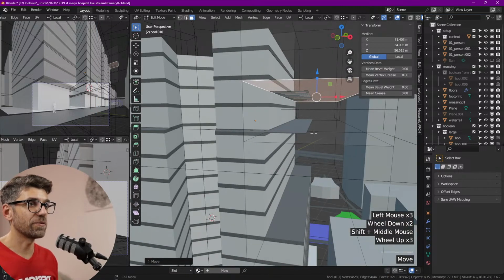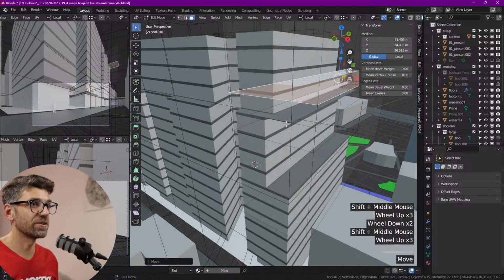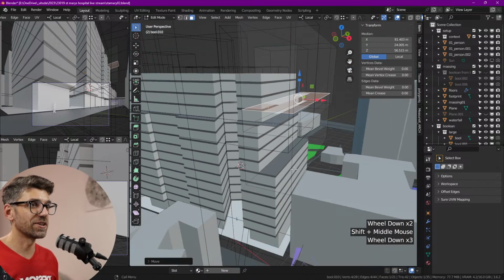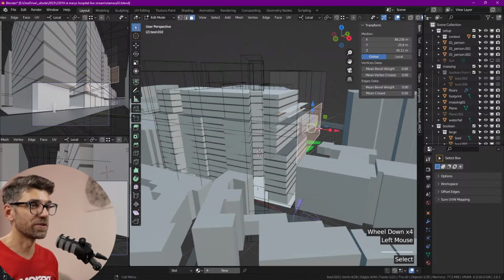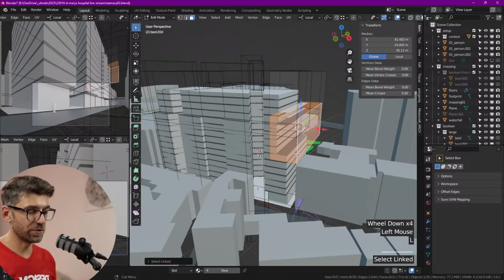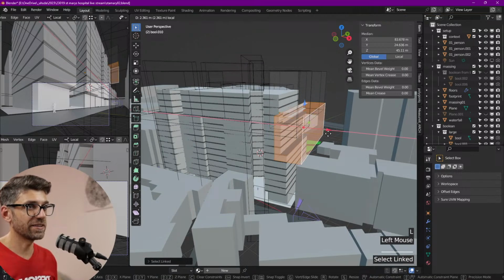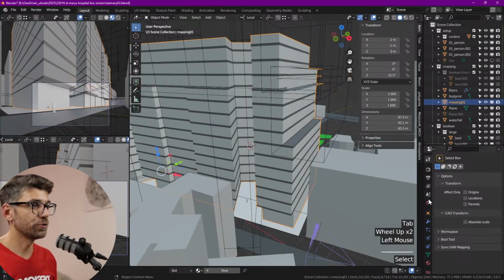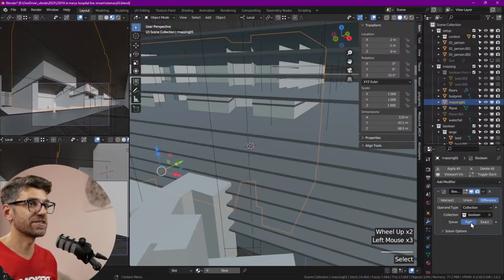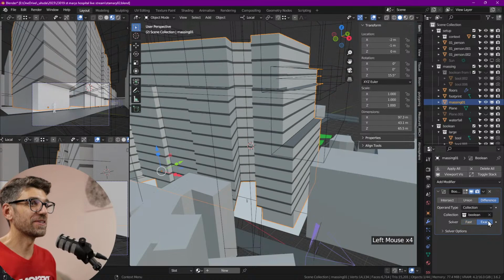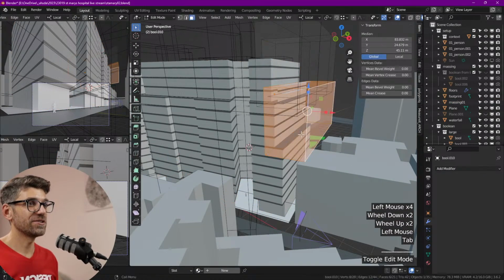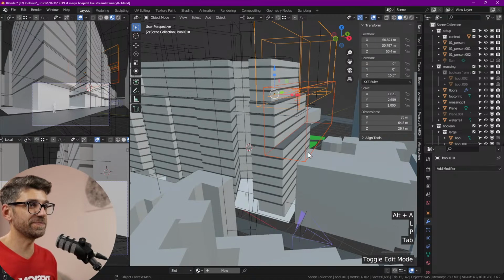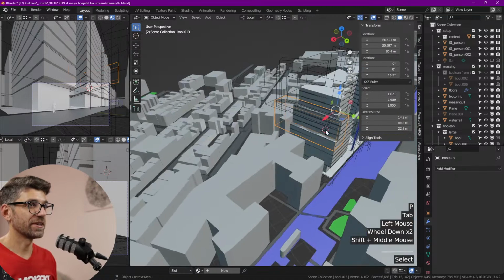Let's carry on here. So yeah, we're starting to get a few errors here, right? There's some area in there that's being extruded, and because of the way those things are aligned, our booleans start to fail somehow. So we have to understand how to make that so it doesn't fail as much. The easiest try is to go back in here and try the fast solver, and it totally fails. So that's not going to work. So then we will do what we should be doing. Select this box, separate it. And now it's working perfectly when it's its own object.